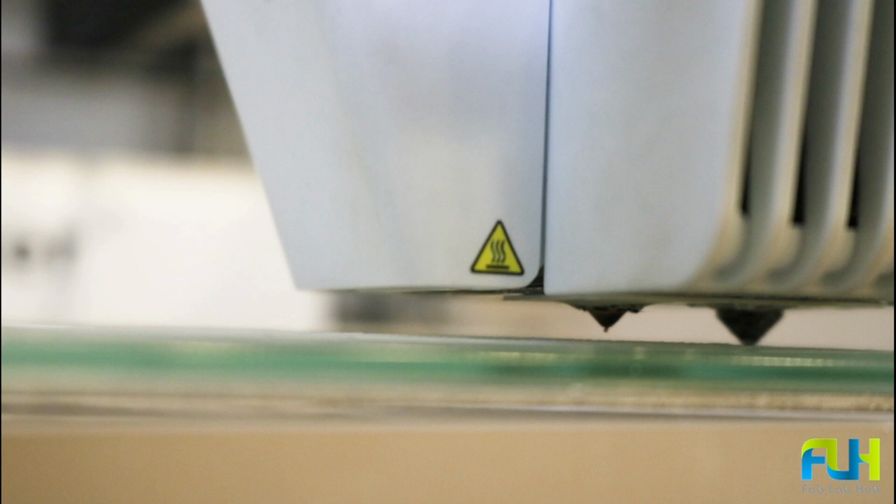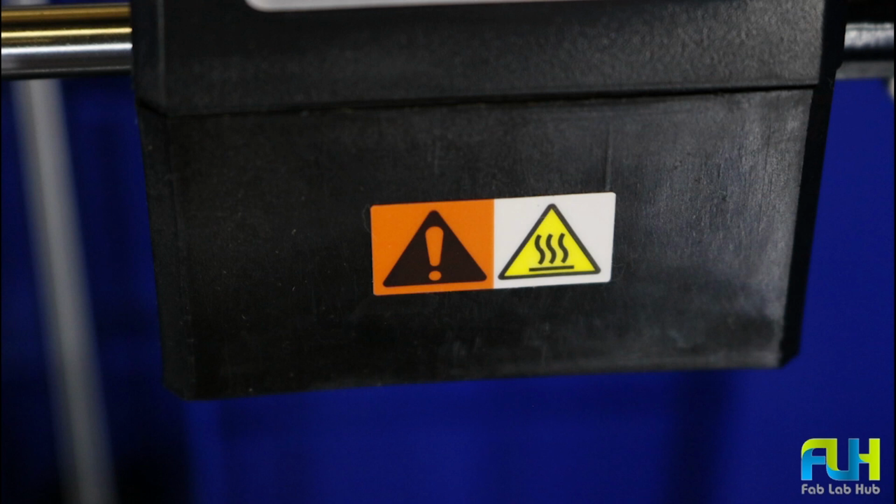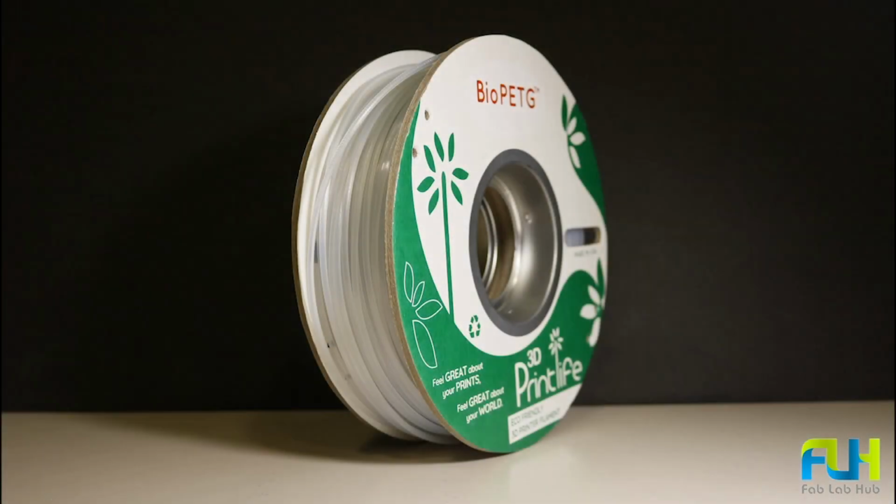PLA is one of the safest materials to work with. Not only does it not produce toxic fumes while printing, but it is biodegradable and food safe, provided proper care is taken to keep the process clean and to seal the finished part. For food applications, however, PETG is the best choice, as it is sterilizable and can be washed in a dishwasher without deteriorating. ABS is generally unsafe for food applications.